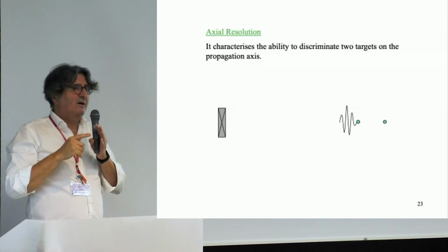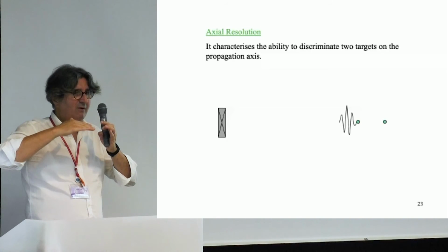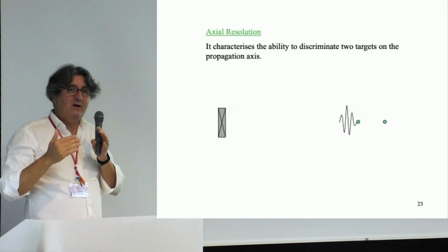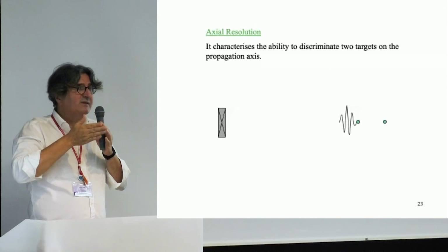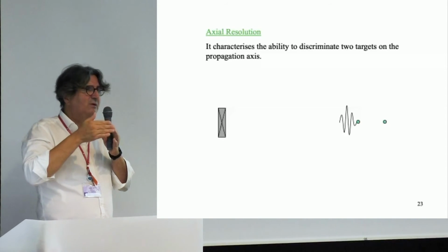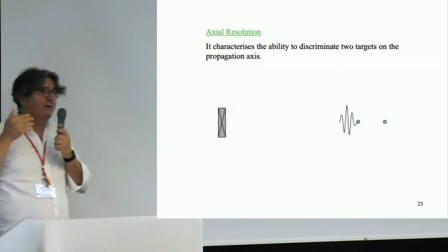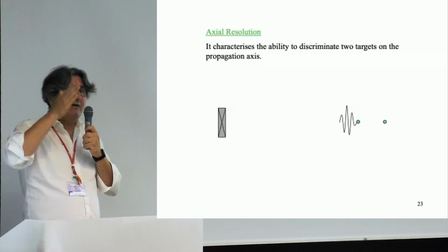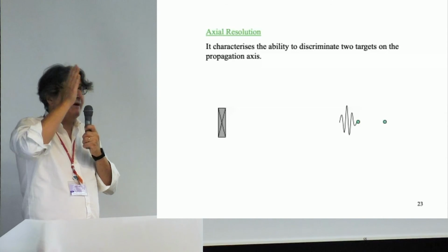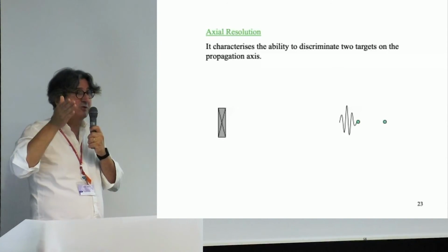The other option is to be broadband, but with low amplitude. The energy, given by the area of your curve, will be constant, but distributed differently. So very often, when you have a large bandwidth, you have low sensitivity, and when you have a narrow bandwidth, you have high sensitivity.